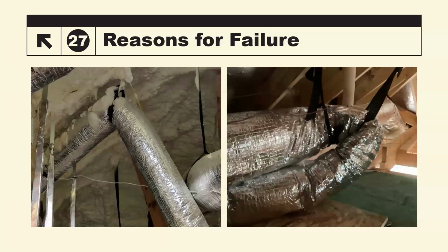And then, of course, missing ducts, bad mastic, holes in the equipment, and holes in the duct are not the only reasons that ducts can fail. As we talked about earlier, duct testing is just a test of pressure differentials. That's all it is. If I'm testing on either one of these ducts, I have to overcome the back pressure due to a compromised duct that's going to either understate or overstate my testing results. It doesn't mean it's going to fail automatically. It means the third party should look at this and say this needs to be fixed. But B, you're doing a duct test and it could be higher than what it normally should be if the ducts were installed correctly.